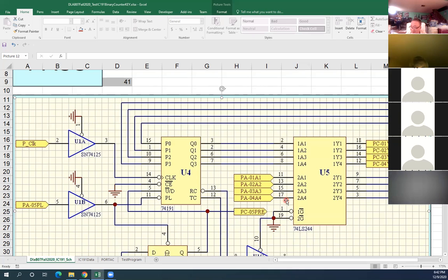Then you have to go to U5 pin 17, and that goes to PA4, which is 17. You will get a 1. You get a 1 there? You must get a 1. That comes from the system, so it cannot be wrong. Right, that comes from the control box. So this is the 1 here and you get a 0 here. Then you have to make sure pin 19 is grounded. If you get 19 grounded, you get a 1 here, you get a 0 here, then U5.